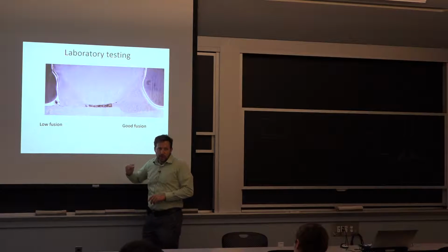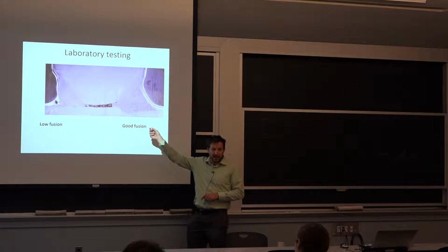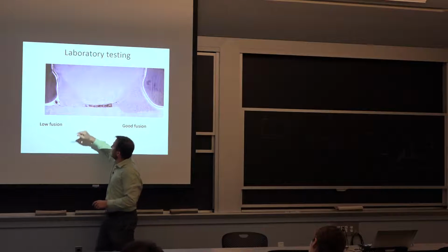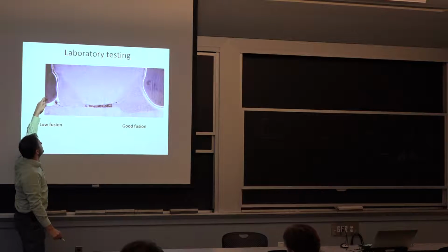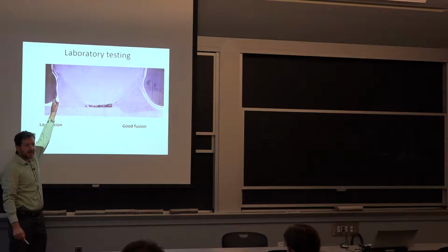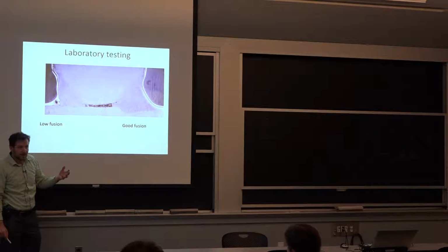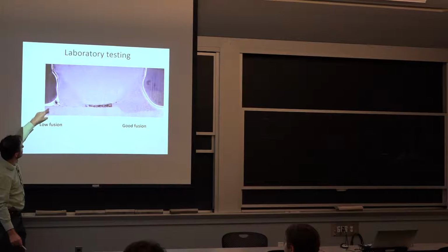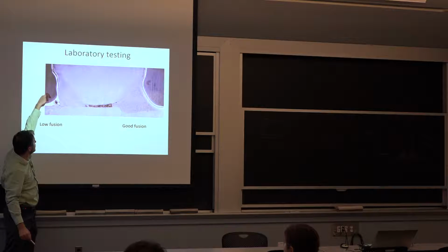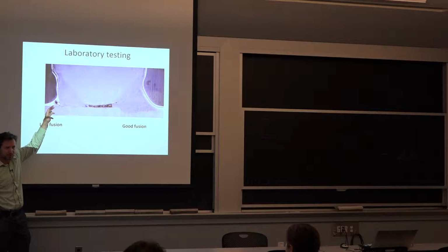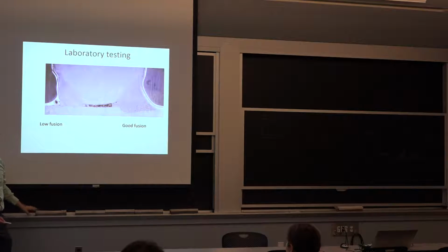Now, on the repair job, we still had some defects. So this is one example. So we have the rounded bar, and the welder, you can tell, was trying to put a lot of the heat into the round bar because that's the biggest sink. This layer here, that's pretty much where the tube ends. Yeah, so that's the end of the tube here. So if he had put the torch and the heat in this zone, he could have had a burn through. So he's trying to avoid a burn through to some extent, but just a little too much.